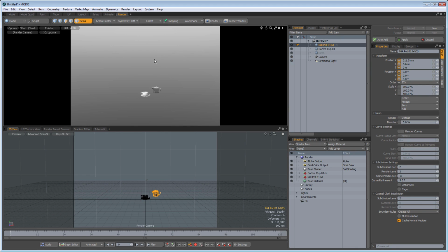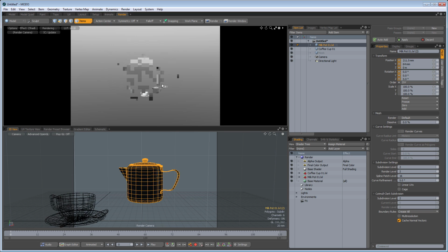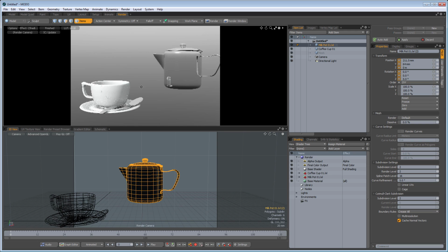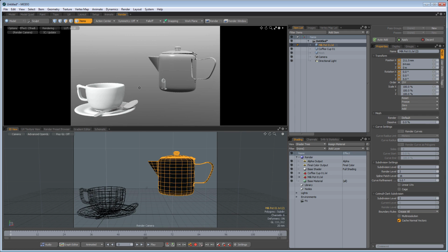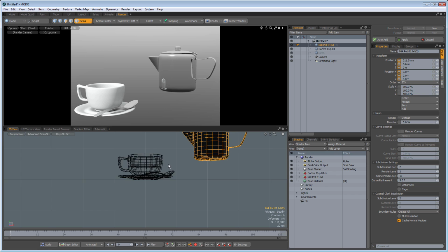You'll see we've got an iterative preview render up here, and if I hit Shift A, I can fit my objects into the scene. Move that slightly. And you can think of Modo's preview renderer as you would the iRay ActiveShade renderer in Max. Down below is our camera view, and you can see that it matches what we see in the render preview window. But we can change this view to a perspective view, or any other view we want.